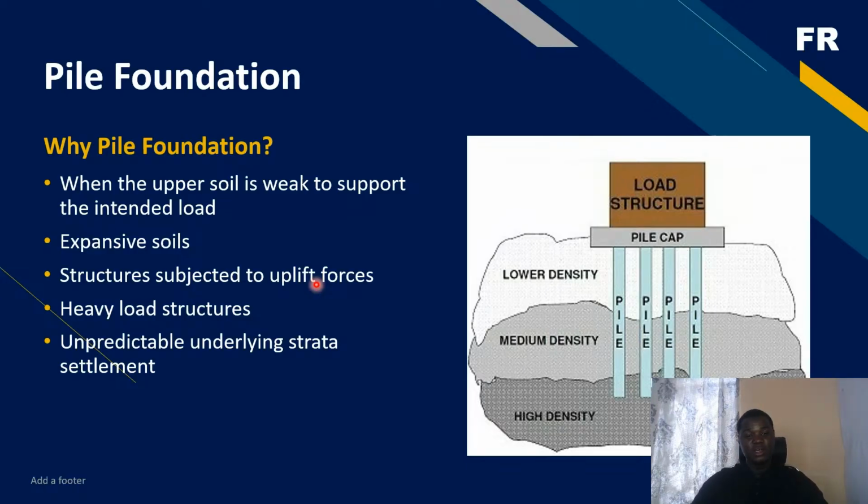A typical example of uplift force is wind, which contributes the majority of the forces on a structure like a transmission tower or offshore platform. In those kinds of situations, it's always safer to support those structures on pile foundation.